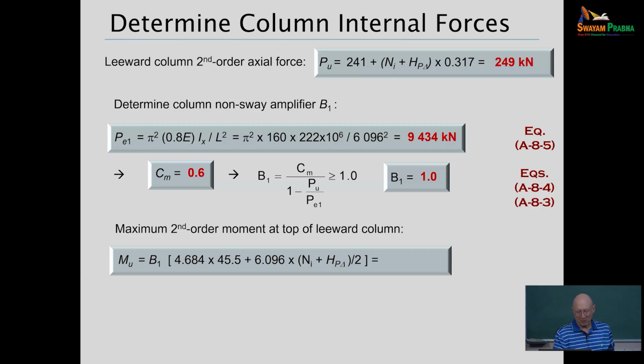And we get half distributed to each of the columns here from the notional load plus the P-delta shear. And so the combination of all that gives us 293 kilonewton meters. That's our amplified story drift method estimate of the moment we need for the design of this column.